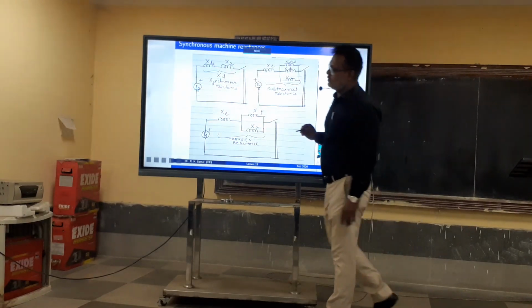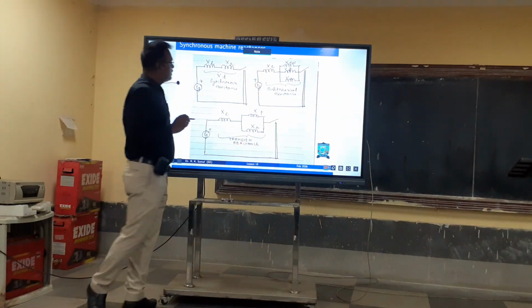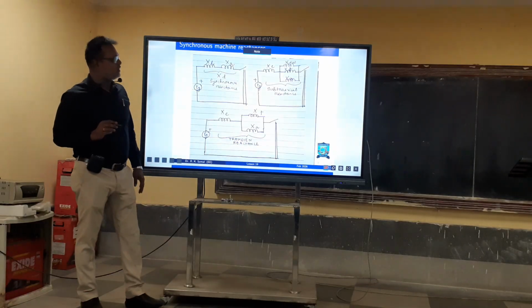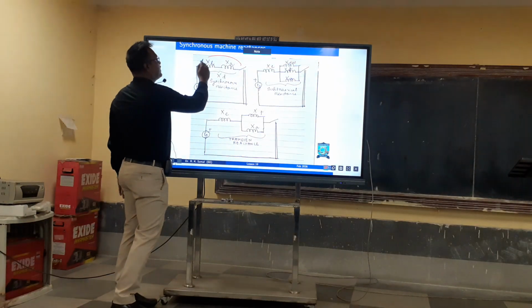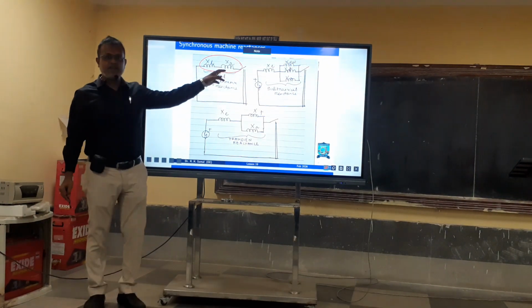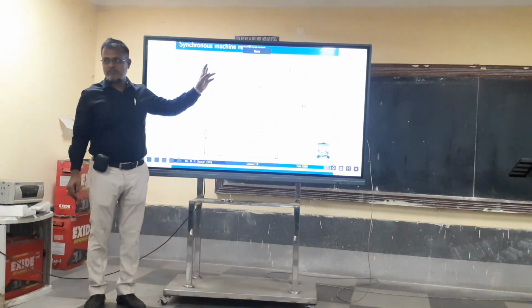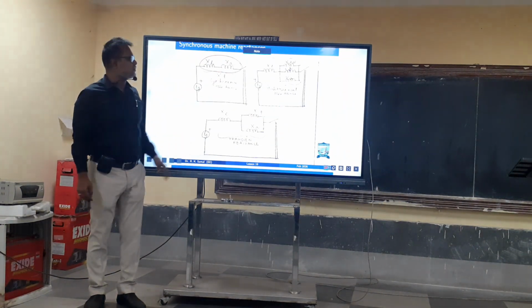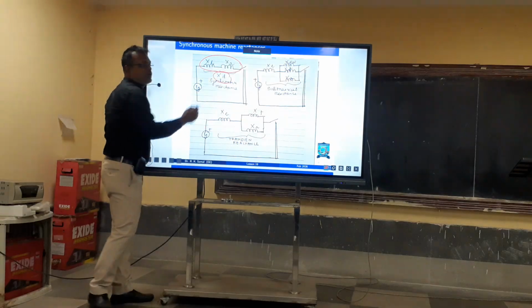During normal operation, from your machines knowledge, you know that the machine reactance is basically the armature reactance plus the leakage reactance. That is during normal operation, and that is known as the synchronous reactance X_S.